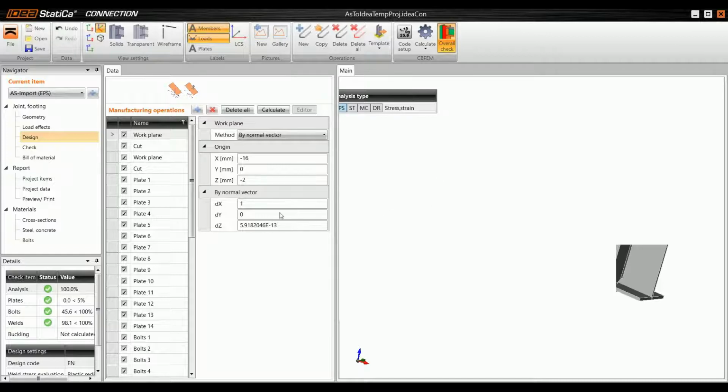We can import any connection from Revit, Advance Steel, and other applications for the application to automatically generate the design. We have templates to speed up the process. And the optimization is, put simply, trial and error. You adjust, you recalculate. This is an interesting idea for the future, to define optimization patterns. But as of now, it works as an application to check what you see.